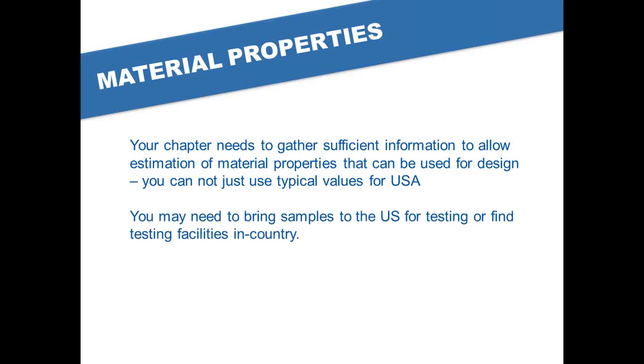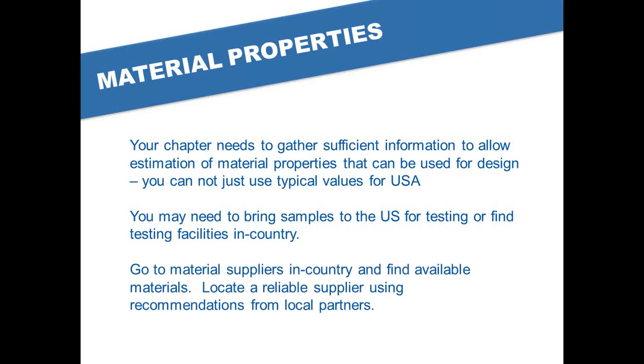So you are going to have to figure out what the actual material properties are. You can't just use typical values for here in the U.S. So you may need to bring back samples for testing in the U.S. or find testing materials in country. And then hopefully you'll get some